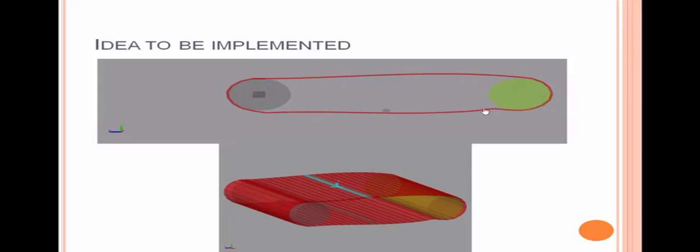It's a little bit slack, so you can imagine if we exert some torque to either of the pulleys, as there's no tension on the belt material, most probably the pulleys will start rotating without having any tension on the belt. There will be no friction between the pulleys and the belt material, so the belt will just stay where it is and no motion will be created on the belt.